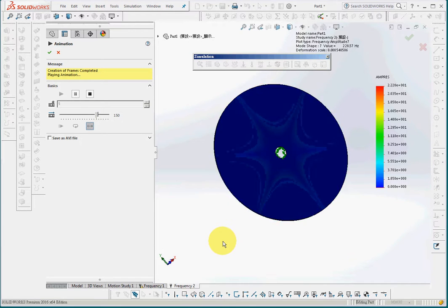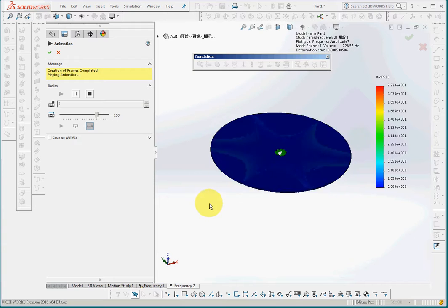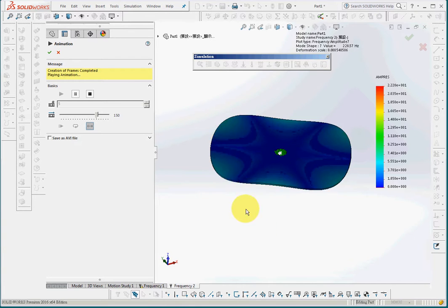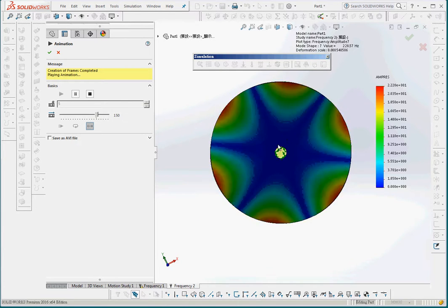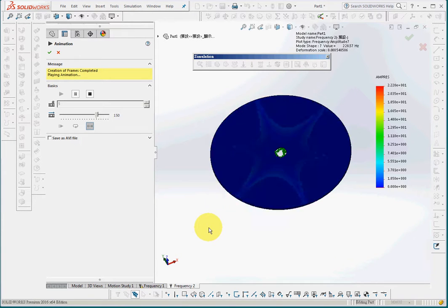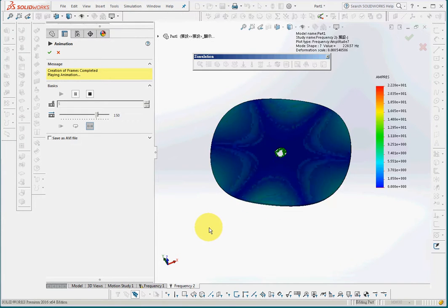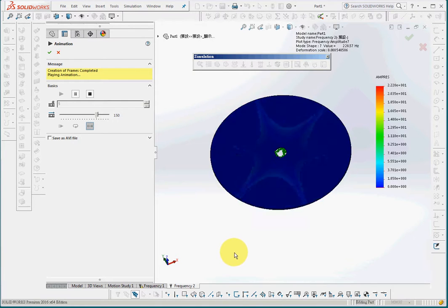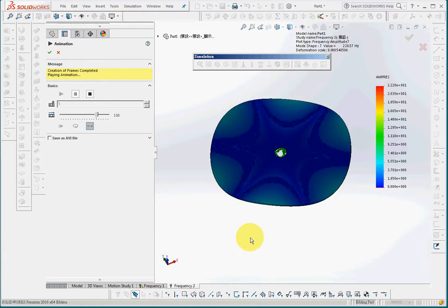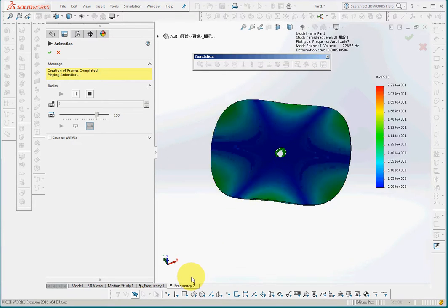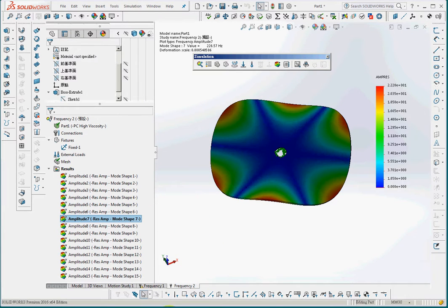In a quarter model, it is 90 degrees symmetric. And in a full circle, in this mode, it is 6-fold symmetric. So a 6-fold symmetry will be symmetric in 60 degrees or 120 degrees, and it will not appear in a quarter model. It is apparent.